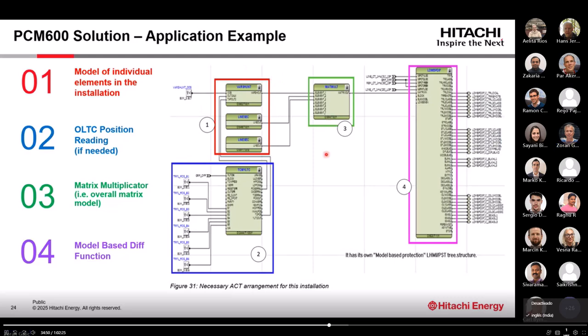Yes, please. Okay, Zoran, Nemanja is here. It is focused now on line differential, but are there in practice some cases where you have some transformation in the zone of differential protection, like some auto transformer or some transformer? Currently, we don't support transformer. Of course, this can be extended. But today, what we release in 227, we can just support the line differential protection.